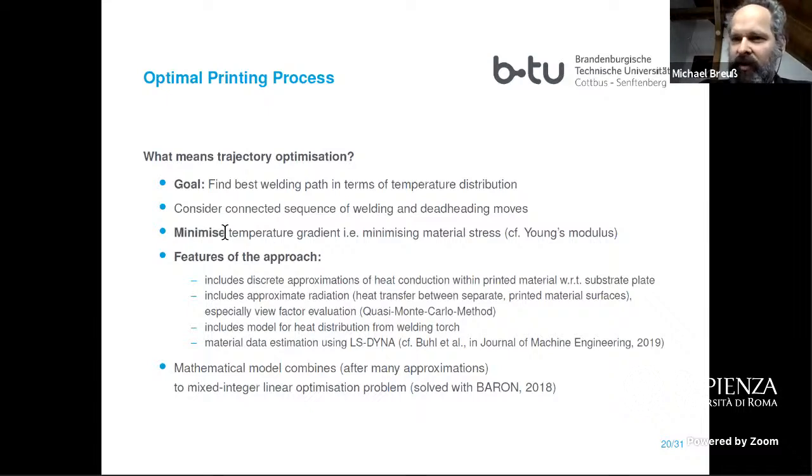So we make a cross section through it, virtually, not in reality, of course. But we want to have a model across such a cross section. So the heat conduction is proportional to the heat gradient at this cross section. It has to be multiplied by a constant for the heat conductivity of the material, and of course times the cross section exactly there.